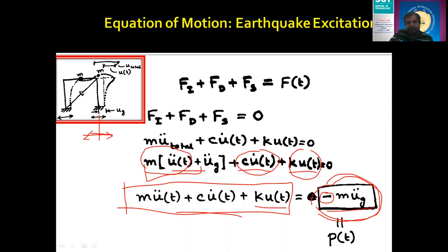So if I initially assume this as the positive direction to establish this relation, and this value comes out negative, it means that at that point in time the excitation will be in this direction. So as such, in a vibrating system, this minus does not have any significance. It just shows the position of the system at a particular time t.